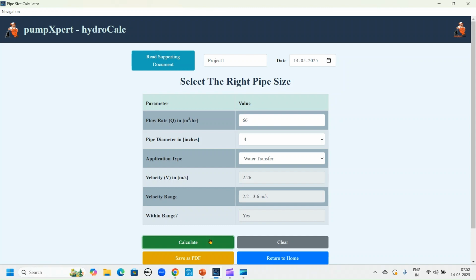One, if I take 178.8 and the entire distance of 460 meters, you will have a different friction loss. And when you segregate it as zone 1, zone 2, and zone 3, then you will have a different friction loss. And this is the right way of doing it. You can experience what the difference will be. I leave it to you to do some exercise and practice yourself, so that you understand the consequences of not zoning it.